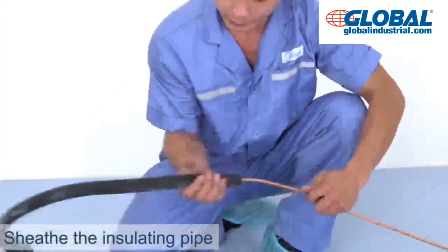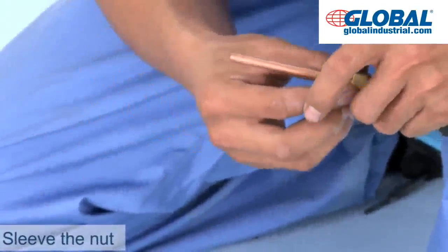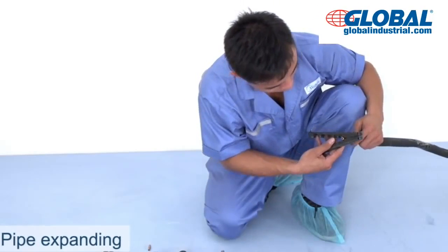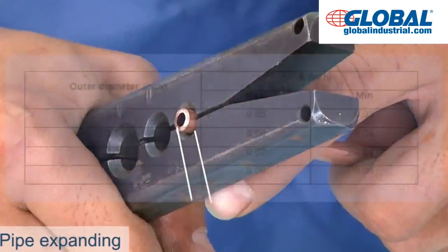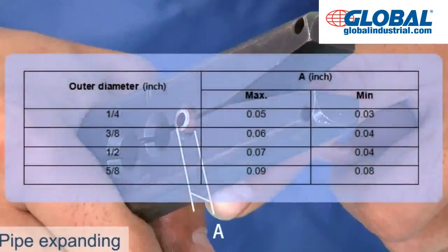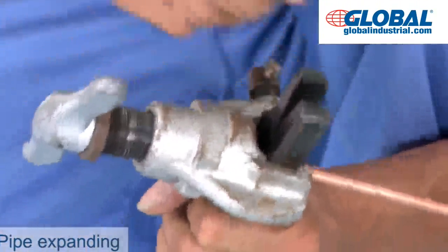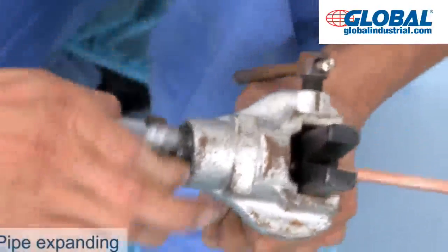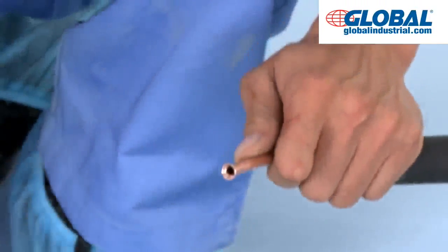Sheathe the insulating pipe. Sleeve the nut. Pipe expanding. Make pipe socket for copper pipe with pipe expander. Firmly hold copper pipe in a die in the dimension shown in the table. Fix flaring tools. Turn the handle clockwise and stop it when it rattles. Pipe socket should be level and uniform, free of crack.